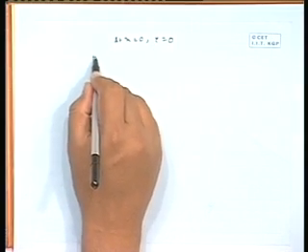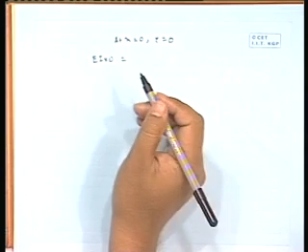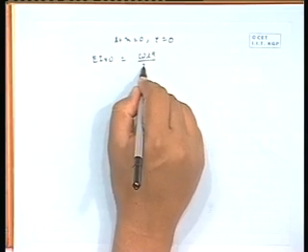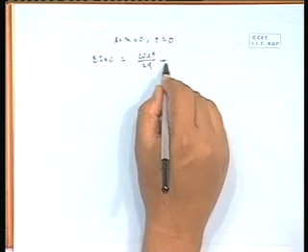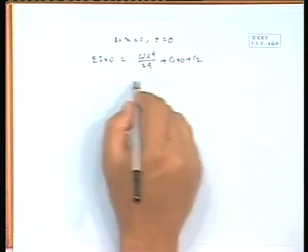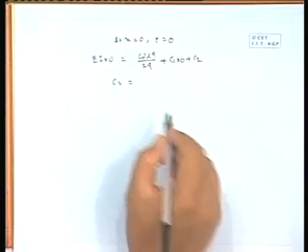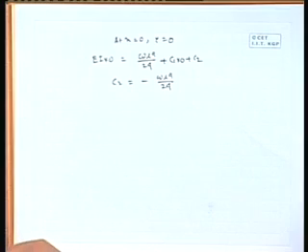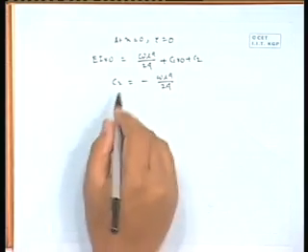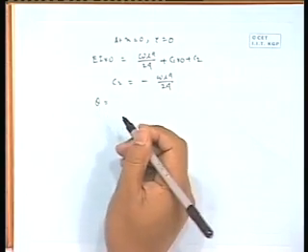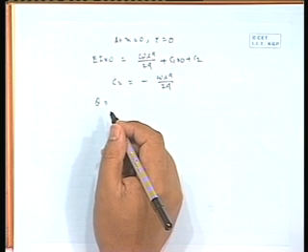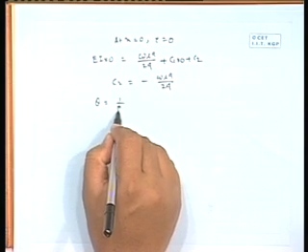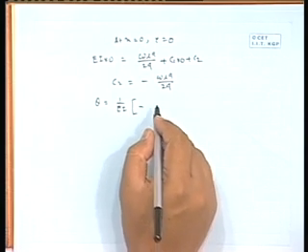So, we will get EI into 0, that will be omega L^4/24 plus C1 into 0 plus C2, or we can get from here C2 equal to minus omega L^4/24. Or these values we can put in the expression of slope and deflection. So, it will be 1 by EI minus